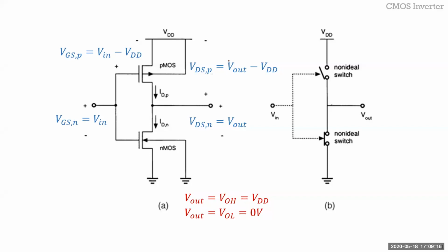And the CMOS idea is very simple, obviously. So you have the complementary switches. You have a switch, the NMOS, which turns on when the Vin is, let's say, high. But during that time, the PMOS switches off. And when the input is low, the NMOS switches off and the PMOS switches on. So that way, only one switch is on to charge or discharge the load capacitor here.